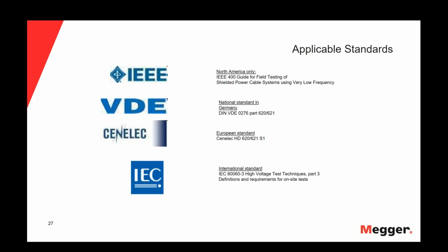The applicable standards for the VLF are the IEEE 400.2, that is mainly for the USA, Canada, and Mexico. We have also the VDE, that is the German standard. We have the CENELEC, that is the European standard, and we have also the IEC, that is the international standard.